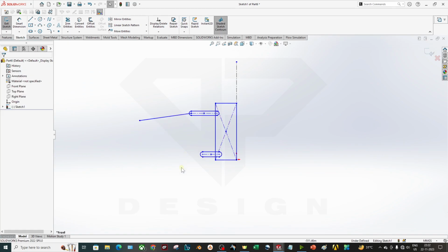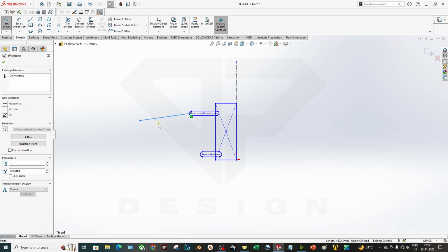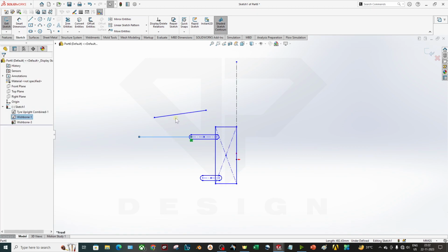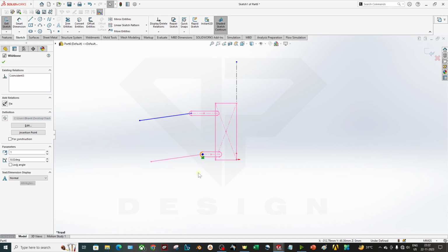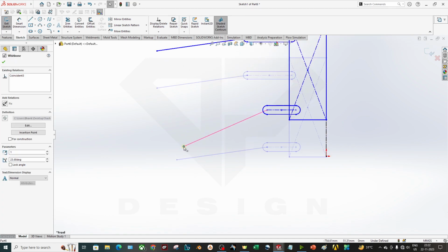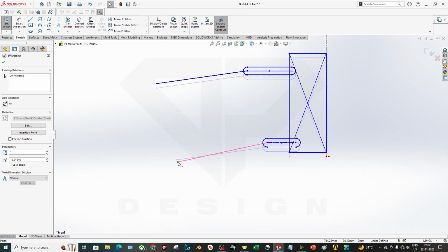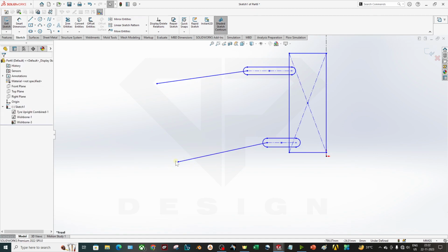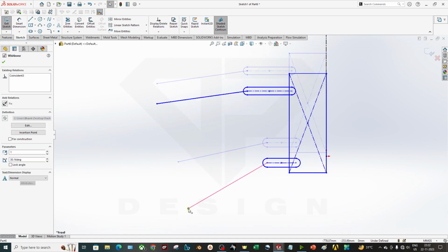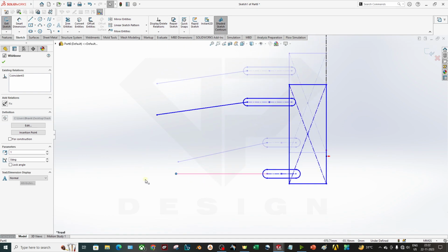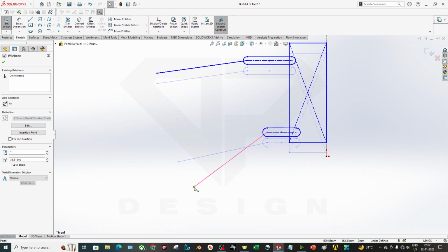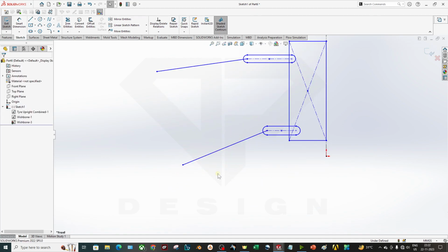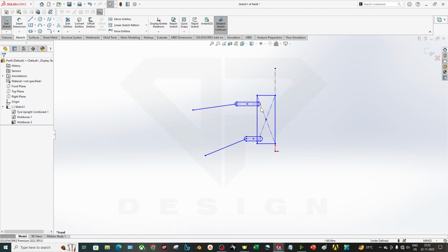Okay, and I will copy this block, paste it around here, and yeah, you have to make this. Now imagine if it was the sketch. What would happen is, whenever I try to move this, there will be a change in the dimension. That's why you have to keep it as a block for the simulation purpose.